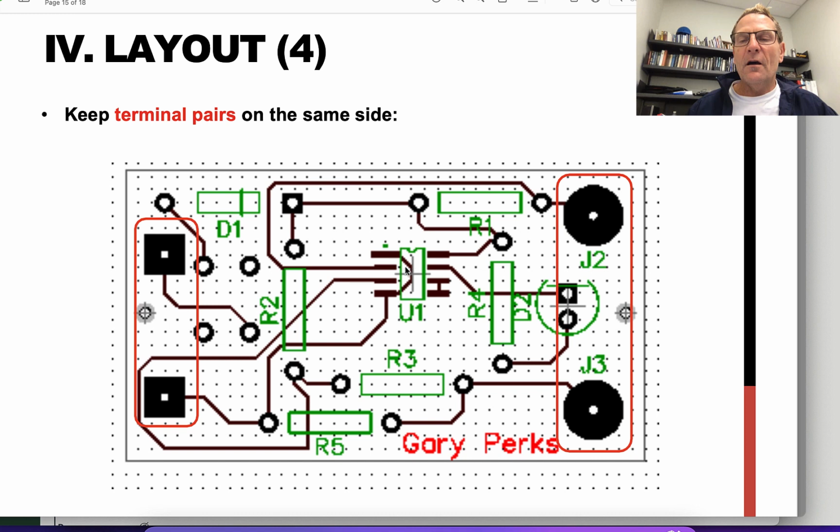We have our integrated circuit, we have resistors, we have full freedom of where to put what, where you would like, within some constraints, but you get to be creative with where you lay out your components on your board for efficiency. And as you can see, there are mostly non-90 degree angle bends on this board. Maybe you can spot a 90 degree angle bend that should be changed into a 45 somewhere. This one right here next to the R5 reference designator you might have picked up. So if you caught that, good eye.